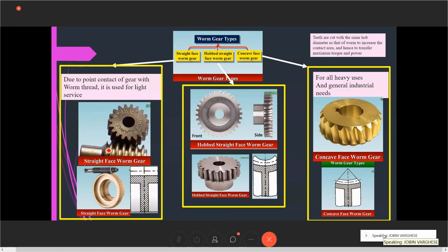So when we apply a worm gear, the major advantage is that it reduces speed in a single step. In a single turn itself, 3000 RPM can be reduced to 50 RPM, depending upon the ratio and how we design it. The second advantage is that much less space is required and the machine will not be bulky, whereas with gear trains there are many gear combinations needed to reduce speed. Another major application is in elevators, because the worm gear will not rotate back. They have a braking mechanism. All these things can be used.